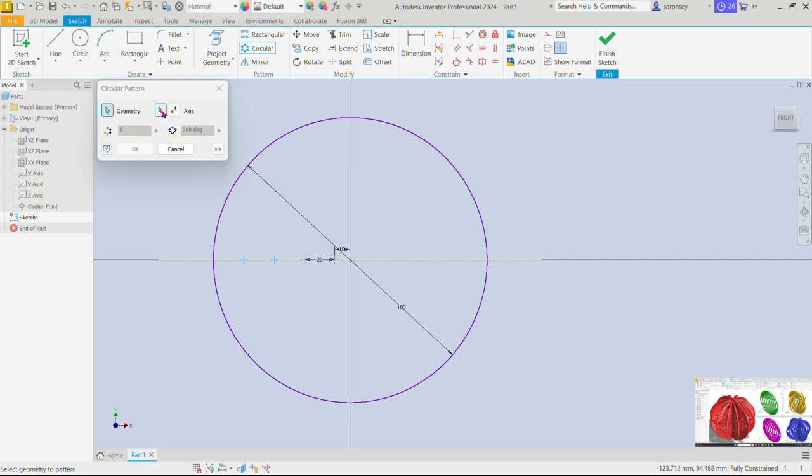And we are also to specify the axis it should go around. We can use this circle or even the origin. So just click. We see previews of that. So we have 6 of them, just like it says here. But we just want 1 here, and we want to maintain this. So let's specify that we want 2. There we have here 1 and another one on this side. It should go around a 360-degree angle, which is fine, until we can OK.